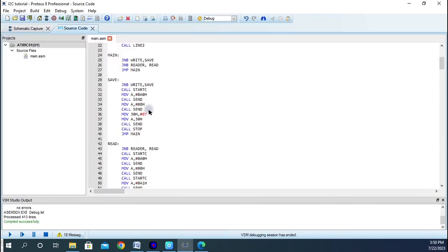Maybe at the time of writing your code, you don't know the value that you want to save. Like here, we already know that we want to save 7, but maybe in your code you don't know the value. Just read that value, put it in a memory register, then save it. Whatever you save there will remain there. When you want to read, you still read it. If you know the data you want to save, you can save directly. But if you don't, you can first move the information, after your calculation or manipulating the code, to a memory location, then you save. Then when you want to read, you read from that memory location that you saved it from.